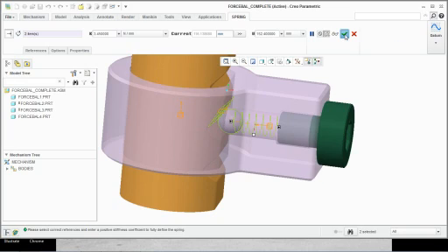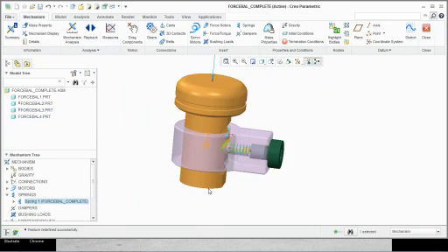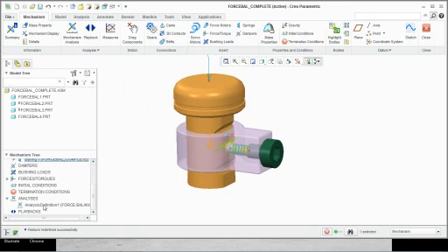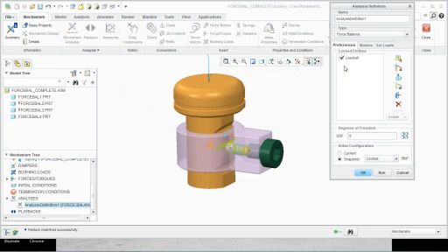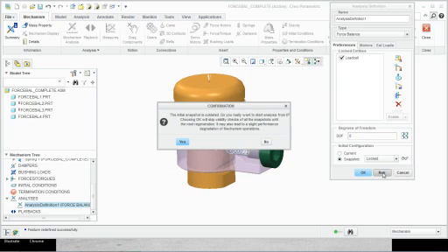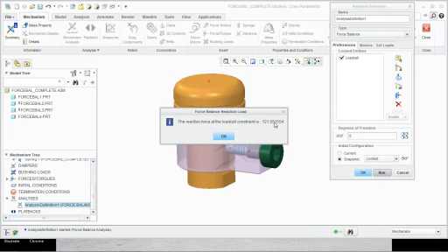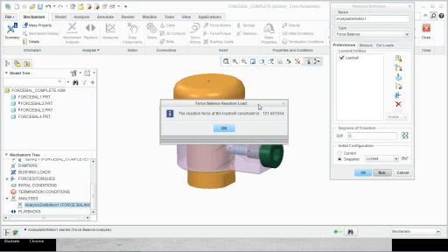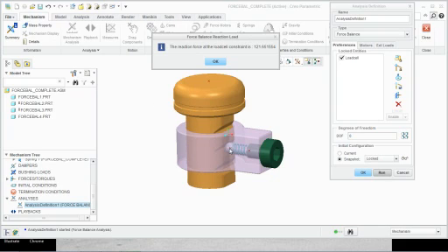Okay. Now, when you want to run an analysis, especially a force balance analysis, what you do is you create these load cells. See that? You just choose force balance and then you create this load cell. Now what is this load cell? When you run this analysis, it's going to tell you the reaction force at the load cell constraint is 121, whatever units you have, say newtons. That means you have to put a force of 121 units wherever that load cell is to stop this mechanism from moving.